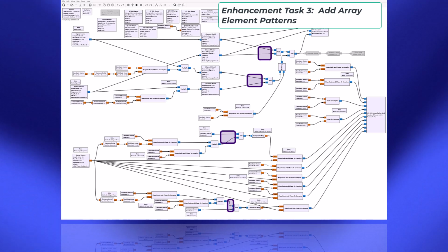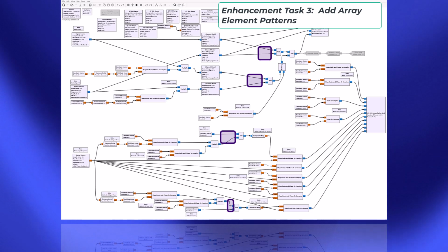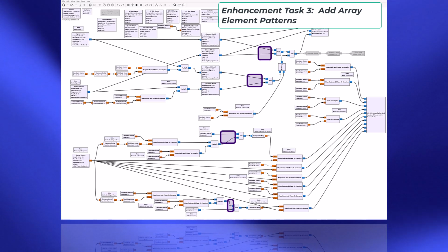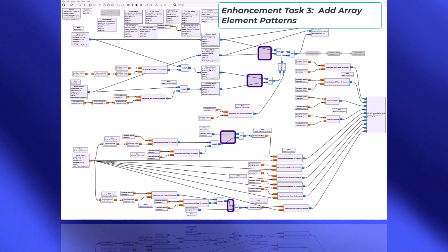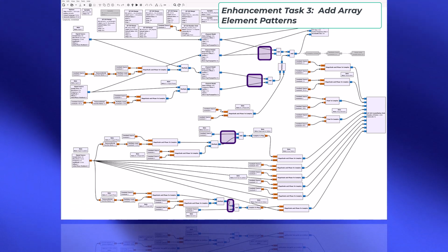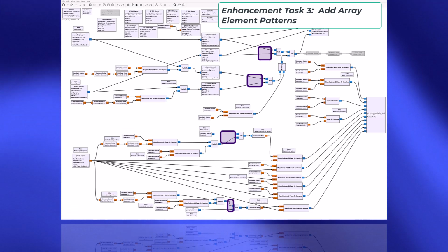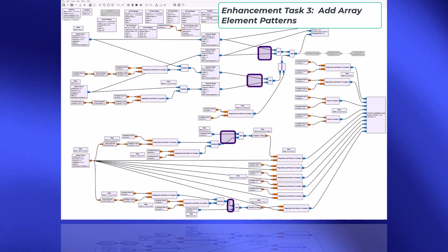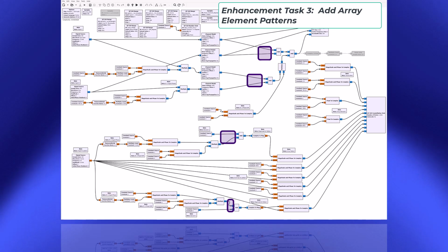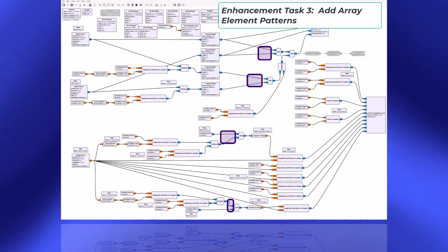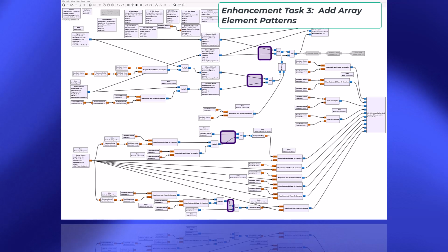And there are a couple places where you need to do that. What I did was make the directional element patterns part of hierarchical blocks that apply a directional pattern to a signal, but that is selectable using a variable in the QT GUI chooser widget or block from GNU Radio, so that you can either apply the element pattern or just leave the original assumption of omnidirectional elements in place. Further, one of the parameters of the directional element block is the direction that the beam maximum of the directional element is facing, which is selectable by a slider.